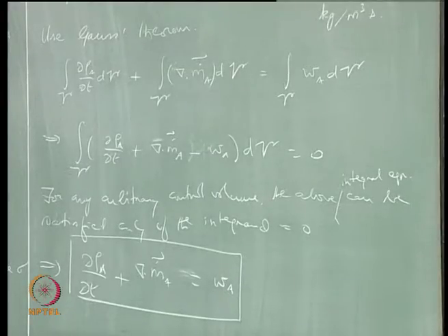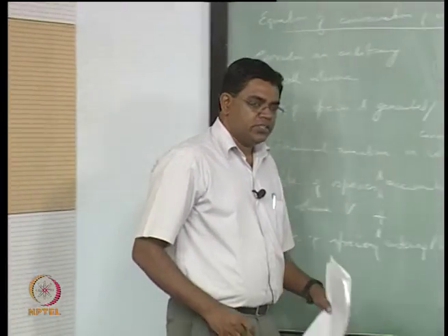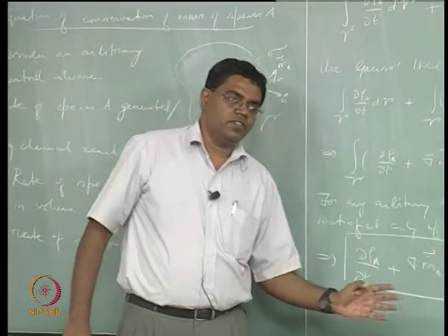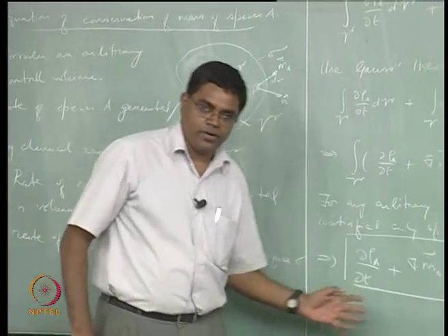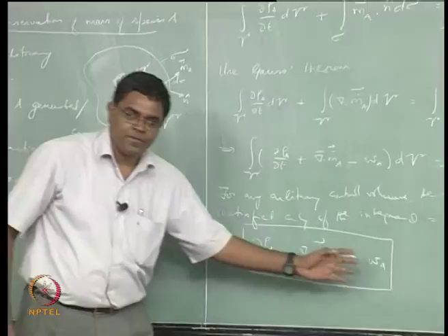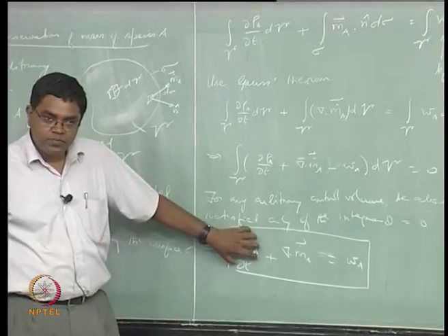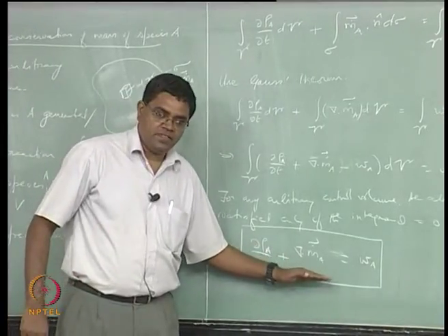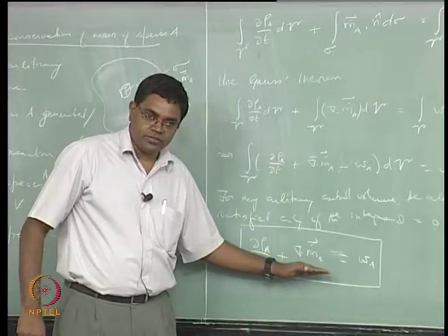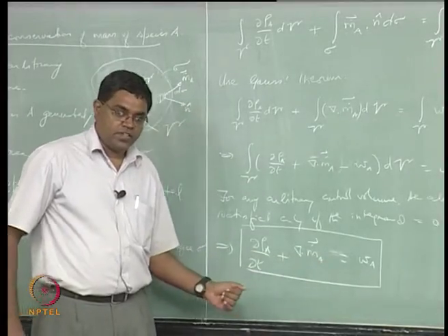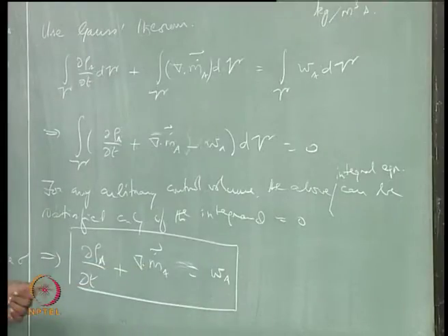All right. We are still not quite looking at the three fundamental processes of combustion showing up here, although we see three terms. This is an unsteady term, but this actually embeds convection and diffusion together, because we now notice that this corresponds to a rho A VA vector, where VA vector is the velocity of species A in a laboratory fixed coordinate system, or a stationary frame of reference.